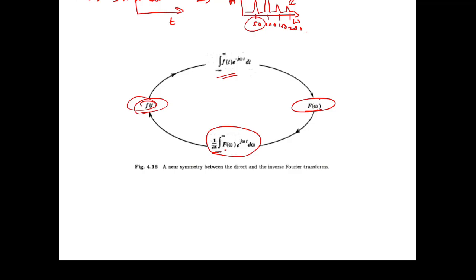So in that case, when you do the Fourier transform, you will see that apart from the signal components which are present in the signal, you also have a component or an amplitude at 50 hertz. So from there, you can say confidently that this signal is corrupted with 50 hertz power line interference. Now, once you do that, you can apply band pass filters.